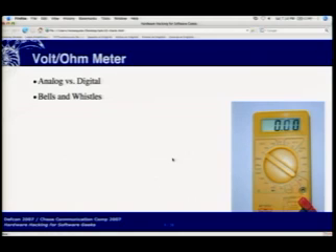Otherwise, these are fantastic. The basic ones, you'll just get ohms, volts: you measure resistance and voltage, current, usually a diode or continuity check. You can get all sorts of crazy features. Capacitance meters are pretty common. Some of them have temperature sensors via thermocouples, which are useful for controlling your toaster oven. No contact voltage. Oh yes, clamp meters for going around something that you believe to be carrying a current can pick up the current by induction.